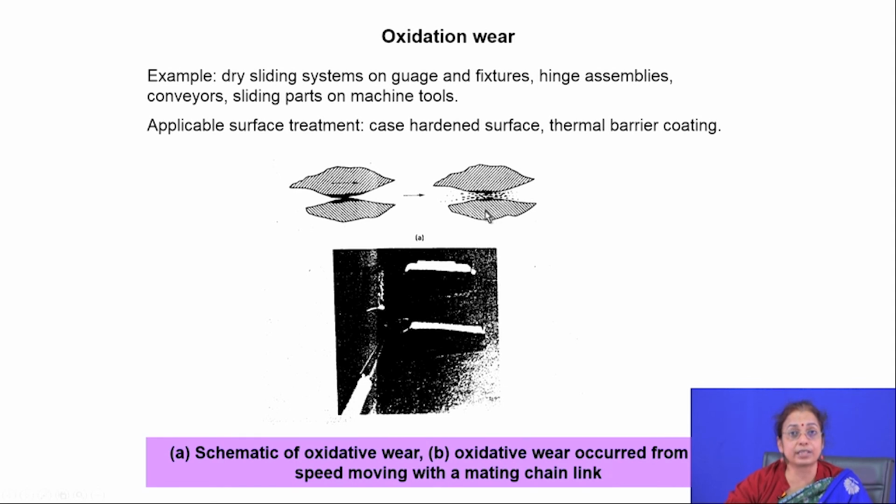So, whether it is oxidative wear or not, oxidation always acts negatively towards wear failure because it increases the kinetics of wear. In abrasive wear the contribution of oxidation is minimum, but in adhesive wear it is maximum, because in abrasive wear the hardness difference plays a very important role, whereas in adhesive wear the joint formation is very important.